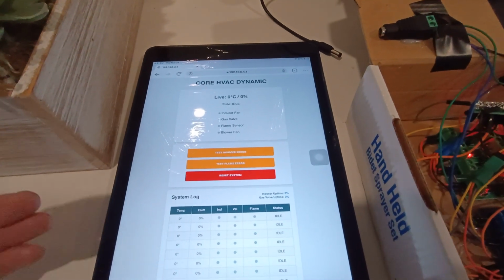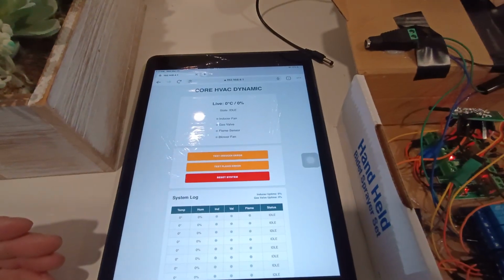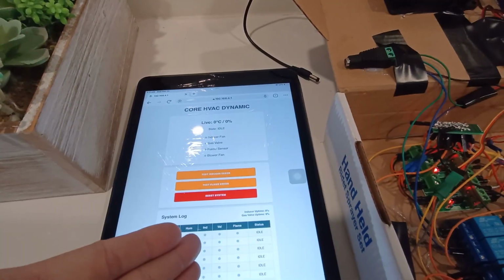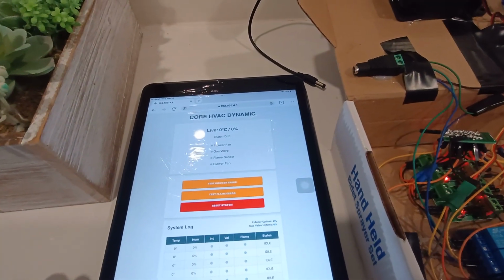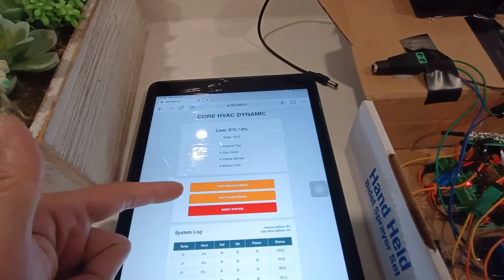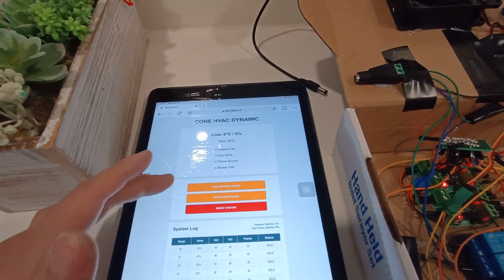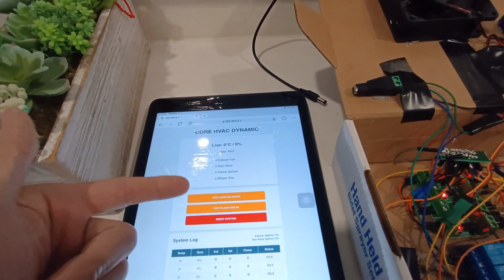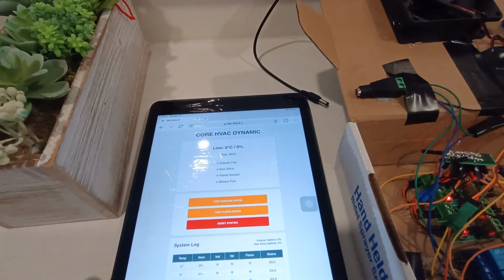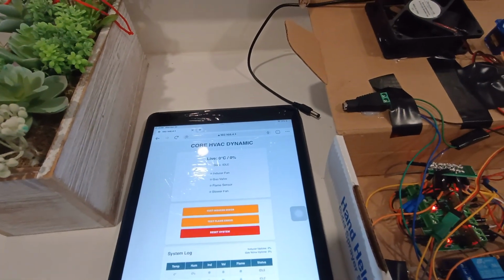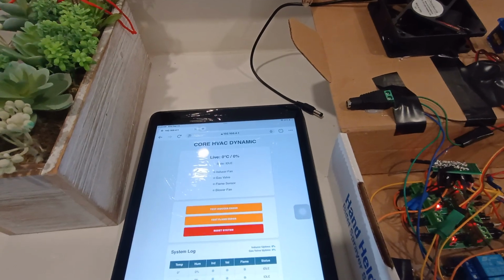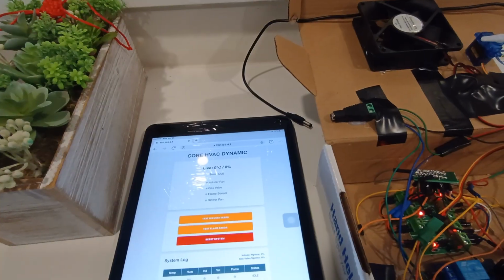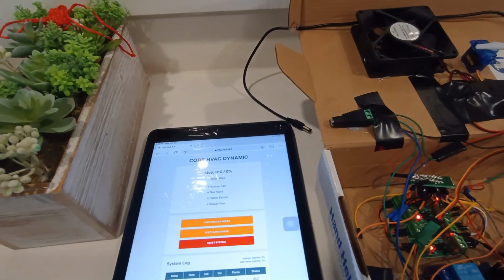And if the system is locked, for example, or any kind of part is failing, it's going to show in this dashboard. Also, I have a testing ability for the system, with these buttons here to turn on or turn off a specific device. For now, I only have two devices I can test, the inducer and the flame sensor. But in a real system, the technicians can have multiple buttons, as long as they have a strong enough power supply and microcontroller.